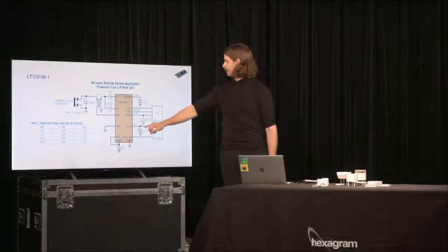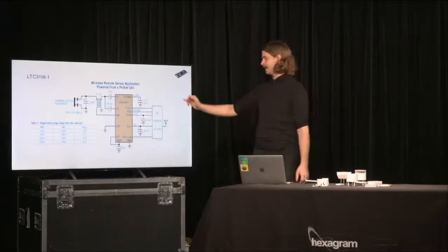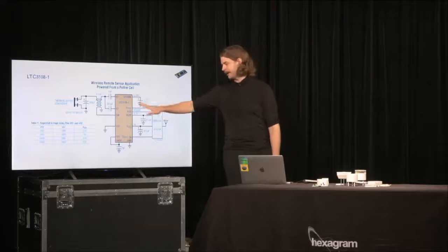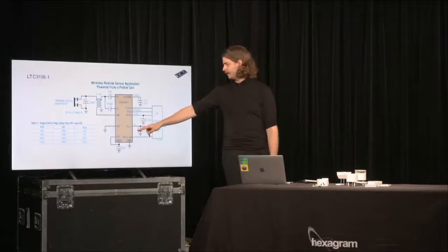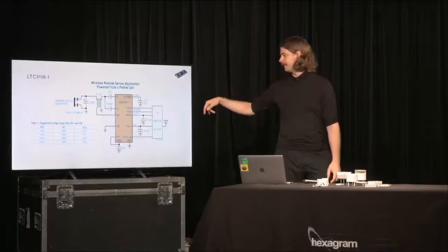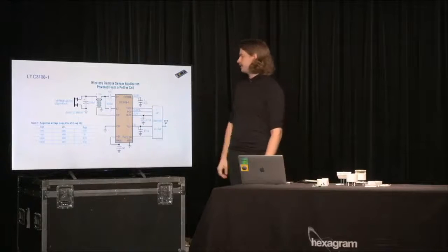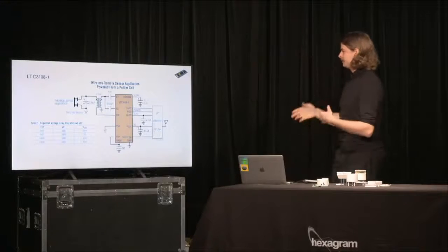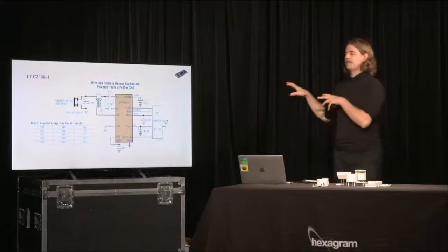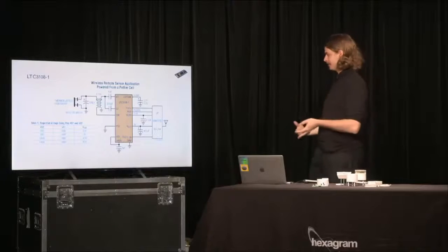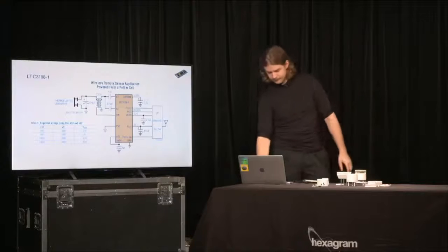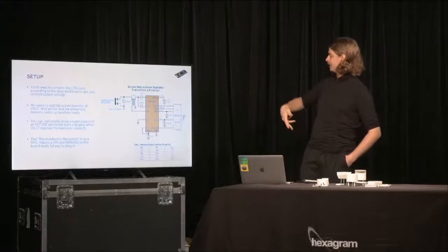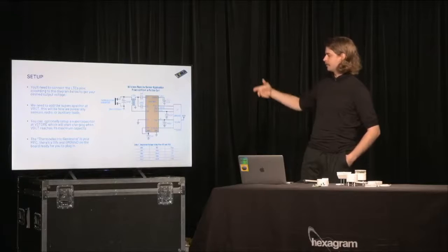You have parts on that board. In the data sheets, it shows you the pins, and these are what you connect. So you can just go step by step, like, okay, I need a capacitor here. You need a capacitor here. I say this all later. You have to connect the LTC 3108 in a certain configuration. It takes some time to fiddle around with and get, but it really is all step by step if you take this route. You just have to follow the steps and you'll get it working. You can refer to this one if you come back to it. It tells you kind of what everything does and where to plug it.